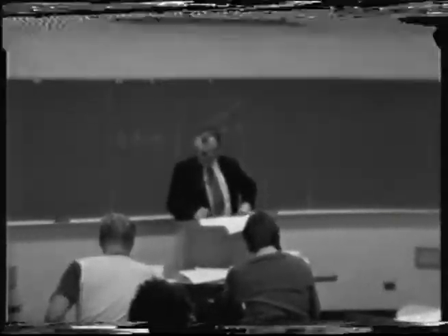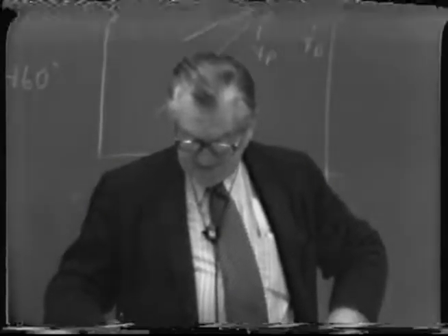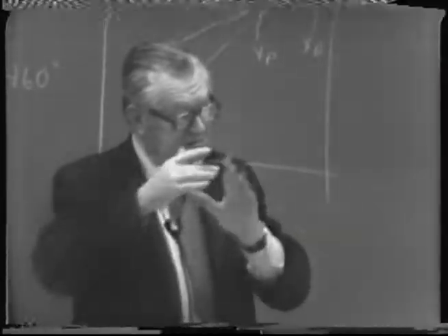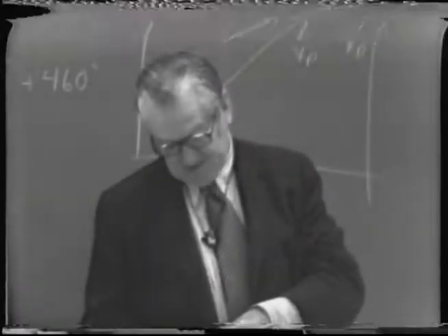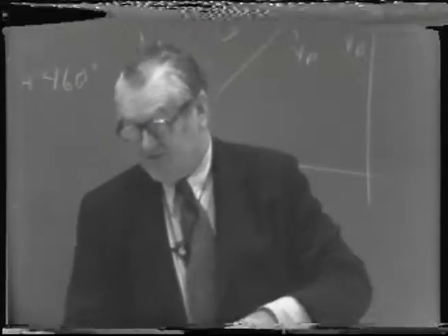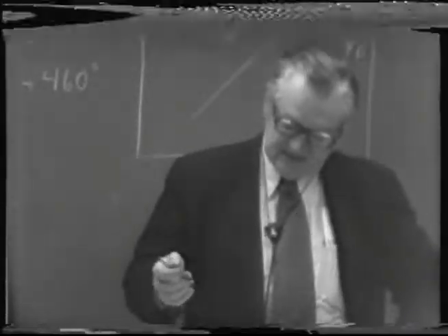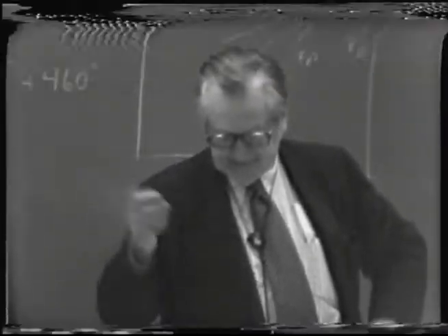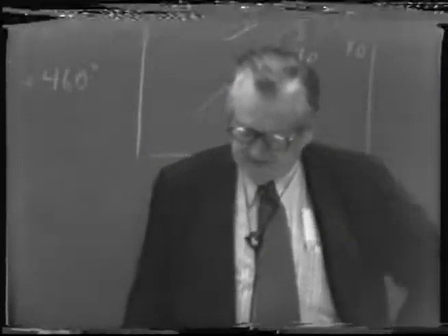This gets into the question of heat transfer considerations, and what we have to do there is calculate the average mean temperature difference of heat transfer between the water and the vapor. You see this little diagram shows the vapor goes in at 173 and of course leaves at a constant temperature of 173, but the water increases from 73 to 133 during the passage. So in that case, we have to calculate what's called a log mean temperature difference. I hope maybe I'll have time to go into that later for those of you not familiar with it. But anyway, it comes out to be about 65.5 degrees Fahrenheit.